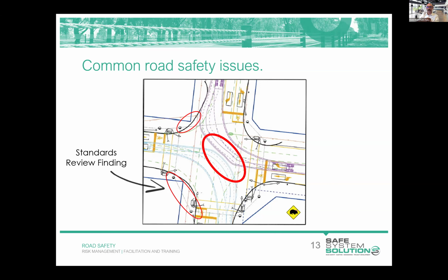And you say that is good practice to do that? It is good practice. The radii that are given in Austroads refer to curb radii. It's a funny term, but I think it's to do with a vehicle making a turn or a U-turn on a roadway and ensuring that it could turn between curbs. So it's measured from the outermost wheel path. To answer that question, that's how we typically dimension the radius.